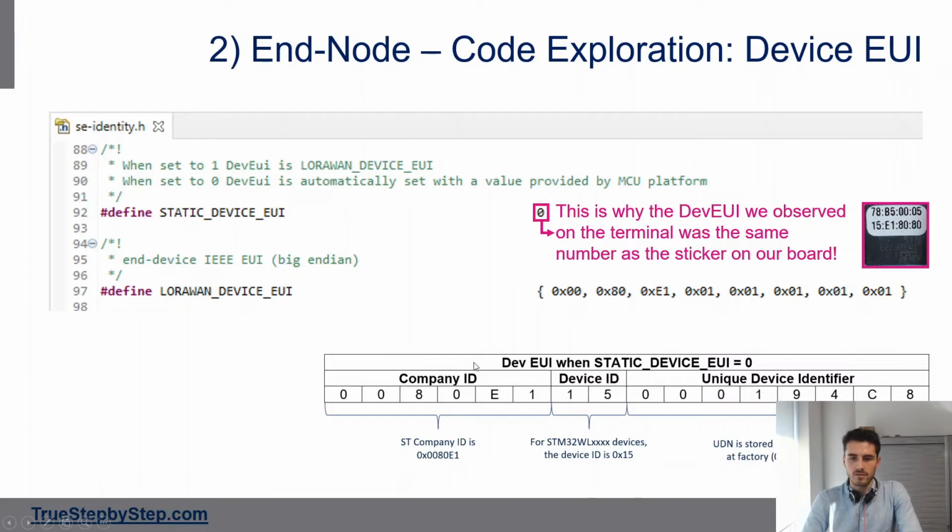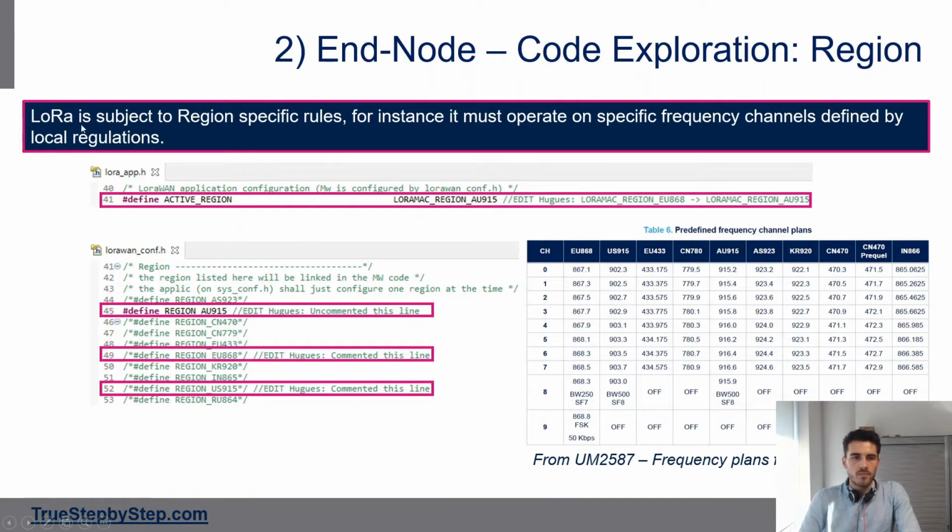This is regarding the device EUI. Yeah, so just pause the video if you want to read something. Then we're gonna check the region. So when we set up the region on CubeMX, it affects lora_app.h and lora_conf.h.